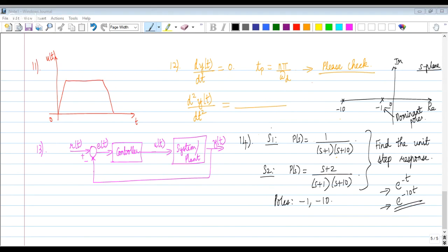Okay, next question on lumped parameter. By and large, in general, variables can depend both on space and time. So when we do lumped parameter analysis, what we are essentially referring to is that we are going to neglect spatial variations and consider only temporal variations. So that we make variables only functions of time. And the consequence is that the governing equations are ordinary differential equations. Okay, so that's lumped parameter analysis.